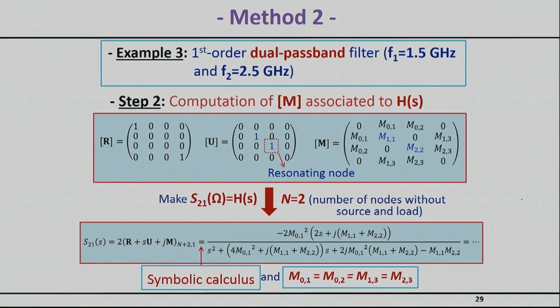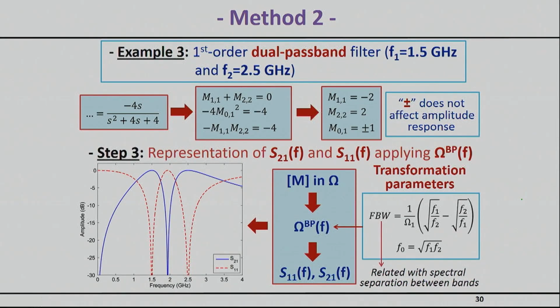And once you go through the technique and through the same math that we have been discussing so far, you will basically find out that you have the 2 passbands. Now, the 2 passbands in this particular example are not greatly defined, are not as sharp as you would like to see them, but that's because this is just a first order filter. So each band has only 1 pole. You could actually make more poles and get a sharper response for each band.